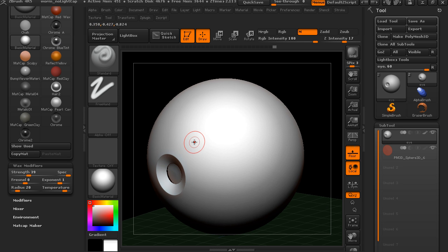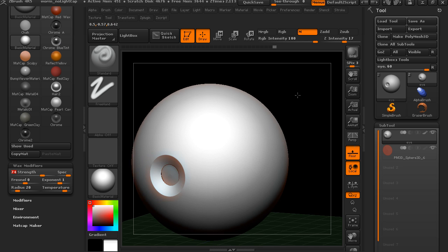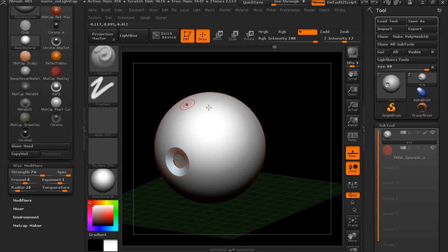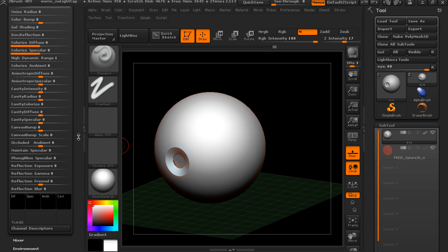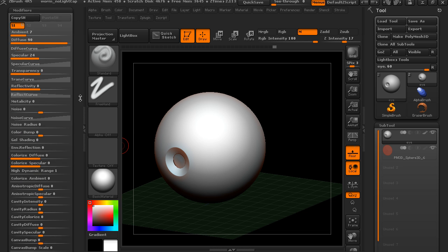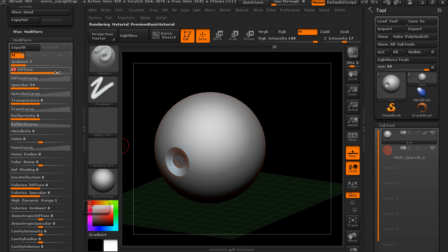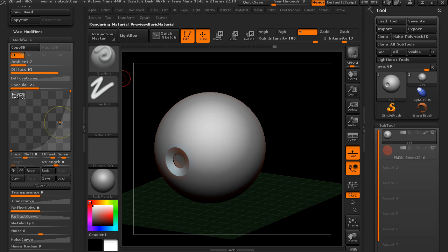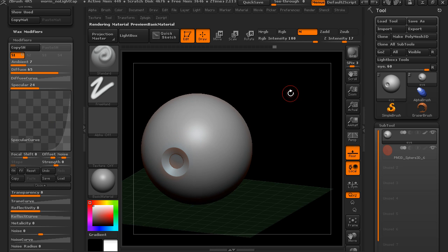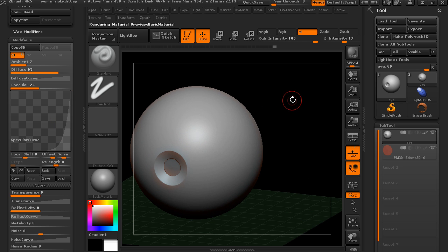You can see there's a subsurfacey look there where if I increase that strength, you get a glow or subsurface glow, and you can take your diffuse down a little bit, make that maybe a little bit more apparent. Maybe take your specular up and increase the shininess a little bit. And you get almost a skin type look starting to happen there with that wax preview.